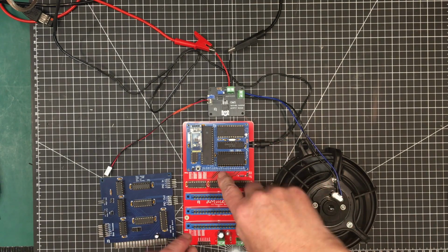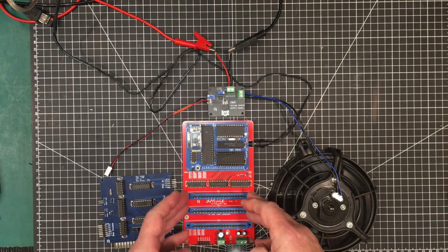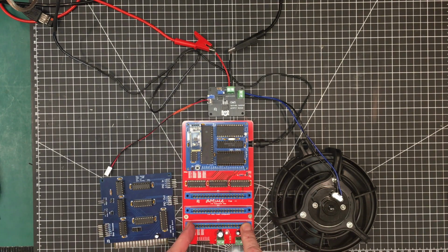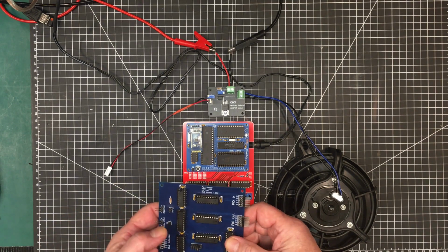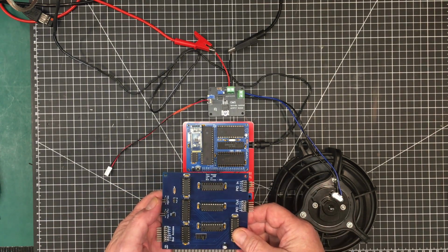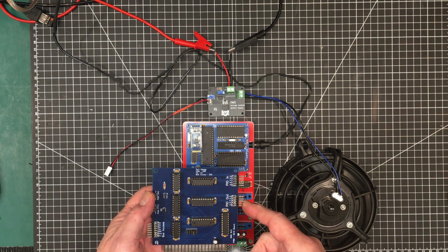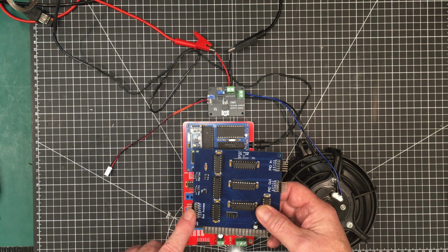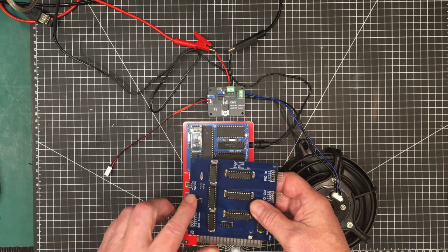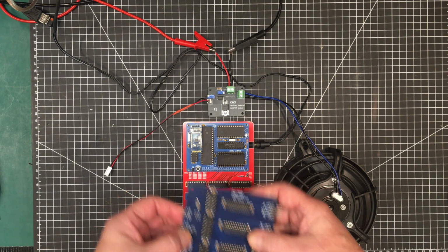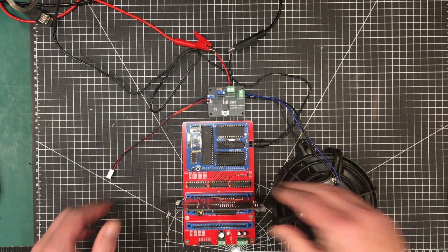And then the I/O comes out and goes through this set here of bus drivers and drives this little 3-slot bus. Now this is one of the cards I made up for it. It's a pulse width modulation output, and it's got 2 ports on it, an 8-bit input port, an 8-bit output port. And it's also got like a bus access, but we're only interested here in the pulse width modulation. And that we'll just put in slot 0 there, or slot 1.